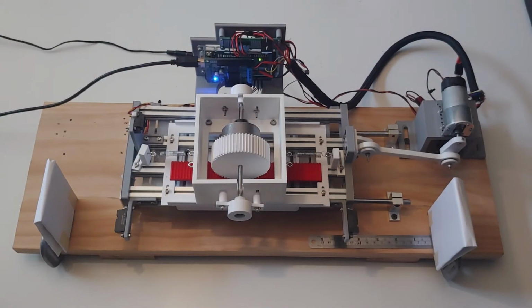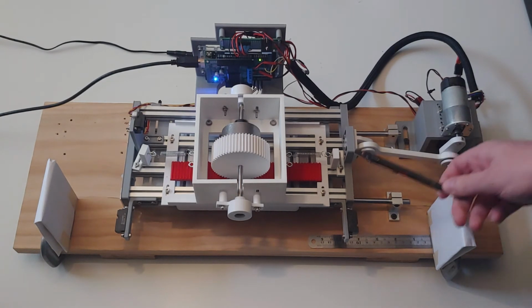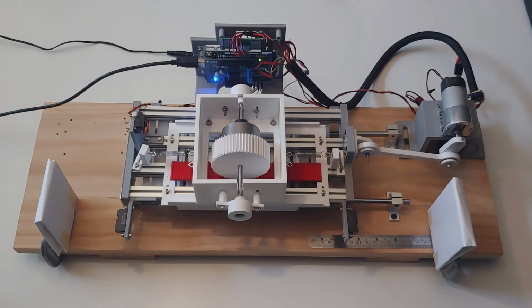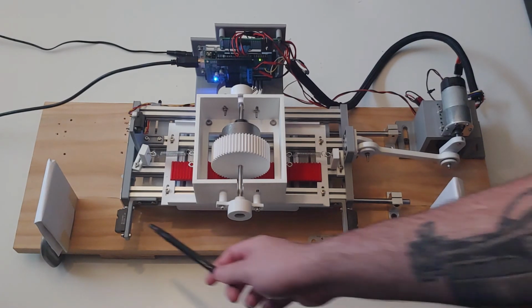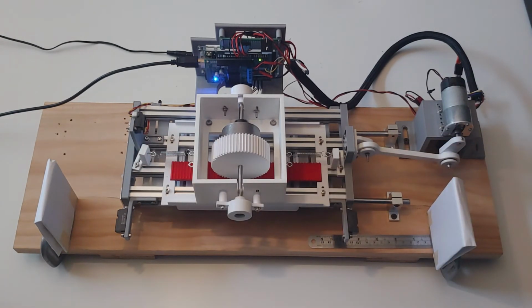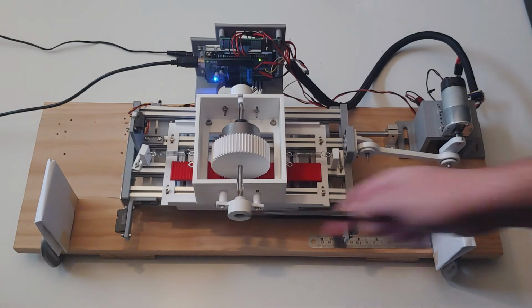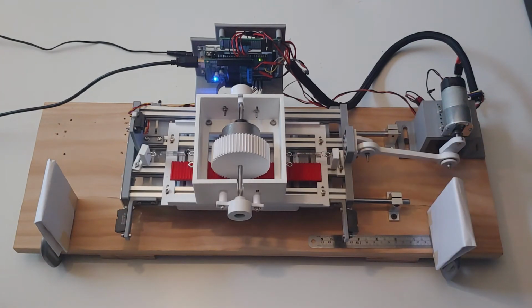Here is the final assembled prototype of the shake table and mechanical inerter-based damping system. For the shake table, we have our linear actuator comprised of the DC motor and this 4-bar linkage connected to the shake table. The shake table itself is outfitted with 3 IR sensors. The outside IR sensors measure the displacement between the shake table itself and ground, which is represented by these 2 walls. The third sensor here measures the displacement between the shake table and the inerter itself.